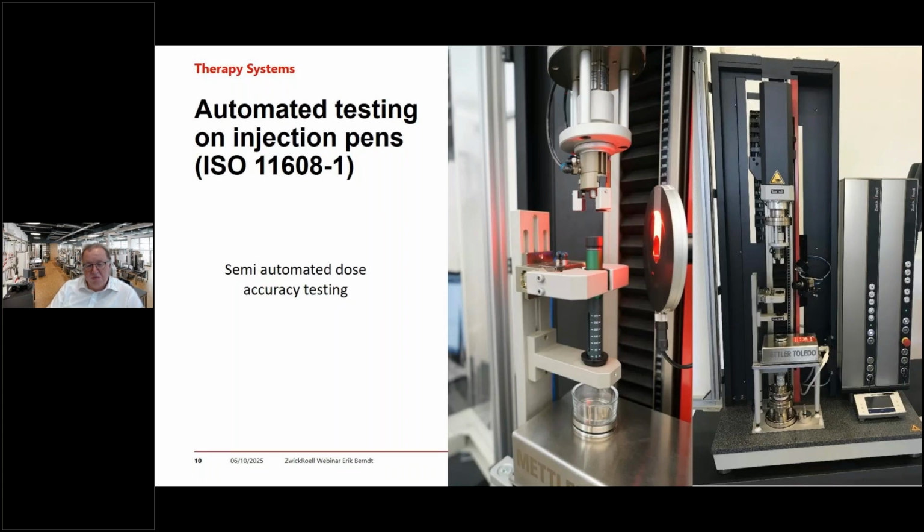But for sure, as I said, to reduce the failure of an operator, we learned from this industry that it is good if the operator does fewer operations on the device itself. And with this, we also entered the dial-in functions to the machine. So the machine can automatically dial in the recipes written in the standard, the V-min, the V-average, the V-maximum. With these recipes, we can measure, and then we can give a thumbs up, thumbs down if it has passed or failed.